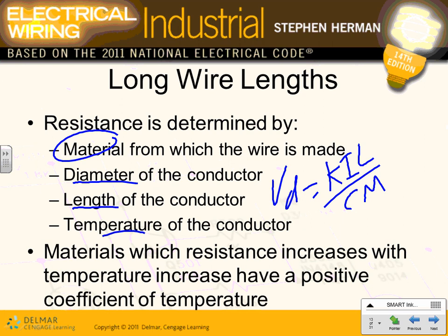For the project that we're having right now, the branch circuits: if you look at the size of the building that we have, if you're within 100 feet or less for branch circuits, almost all your equipment, like lighting and receptacles, you're almost covered with 1.25 for continuous load and so forth. The only place that you need to check for voltage drop is the parking lot, and typically for the parking lot we pull a bigger conductor anyway, like number 10 or number 8, even though we need number 12. Unless you're talking about big projects, yep.